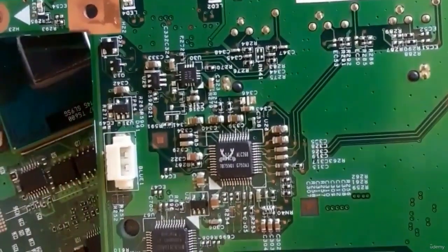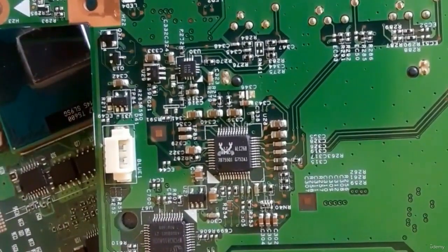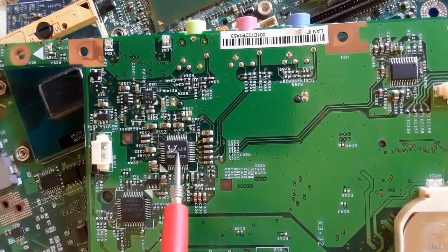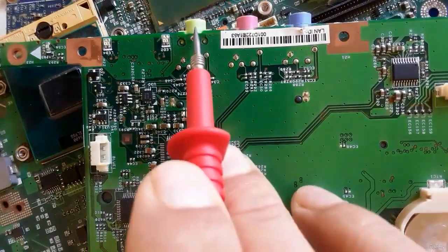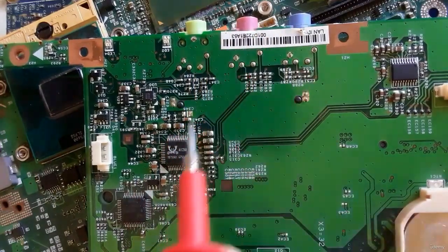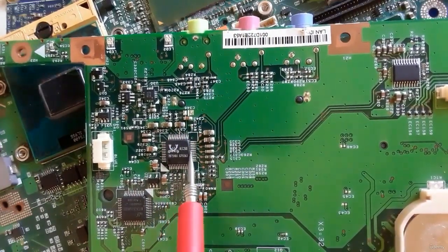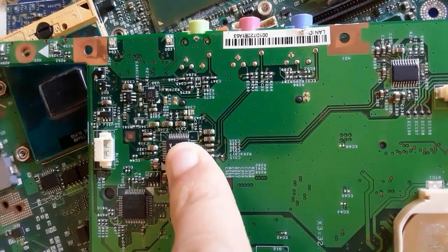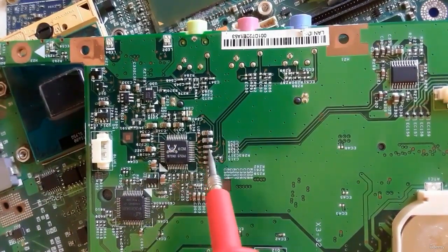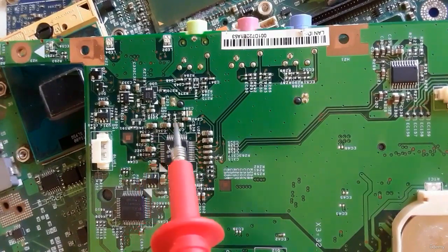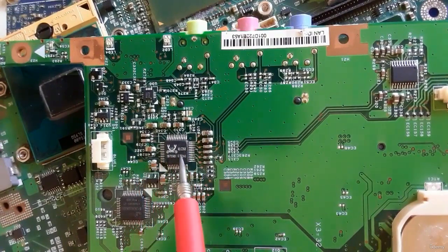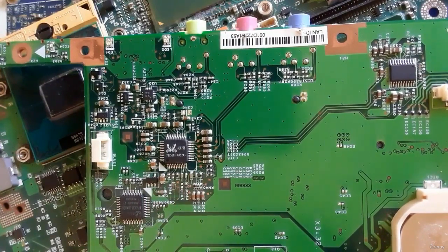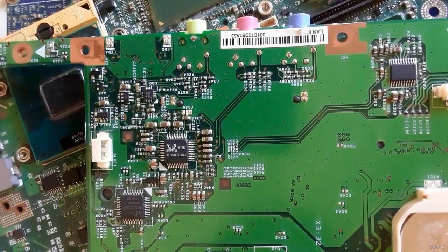Then there is another IC that can cause the failure, the sound IC or the audio control IC. As you can see, it controls these ports. So this is the audio control IC. If there is any problem in this IC, it can cause a dead motherboard or a failed motherboard. Of course, you can check it by feeling it with your finger. If it is very hot, it means it has failed. Or you can check the ceramic capacitors around it. If you find any shorted capacitor, it means the IC is bad. You should replace it using another IC with the same part number or reference.